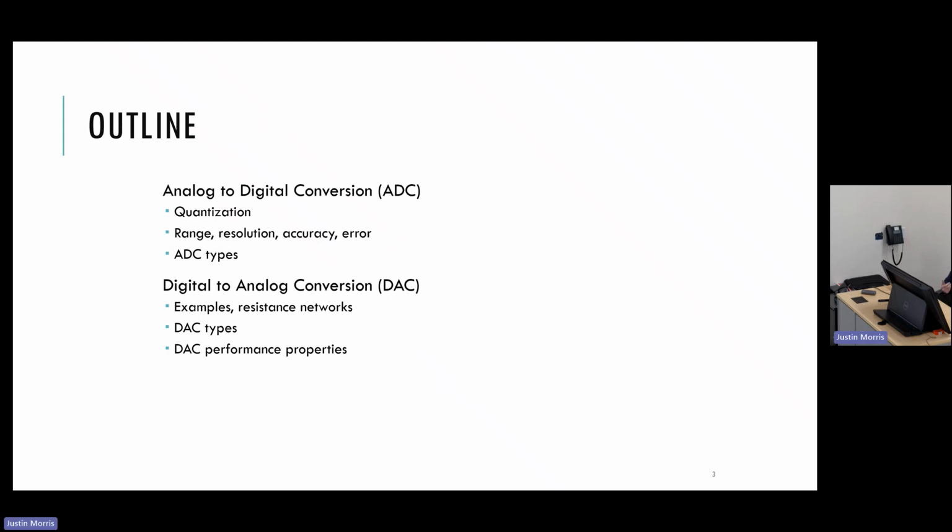But our computers work on discrete digital values, right? So all of our sensors are going to be taking in this analog data, and they need to be able to convert it to digital data. And then when we output it to the actuators, again, they are going to be working in the analog world. So a lot of the times our output needs to be analog, so we need to convert from digital to analog on outputs, and from analog to digital in order to process on inputs.